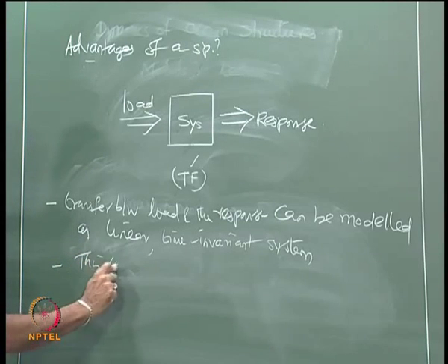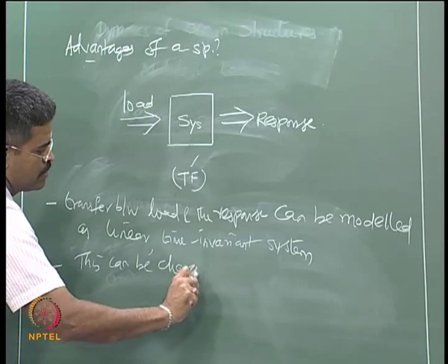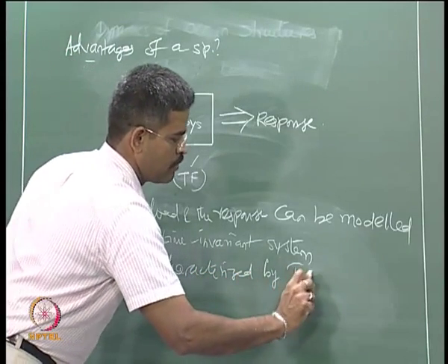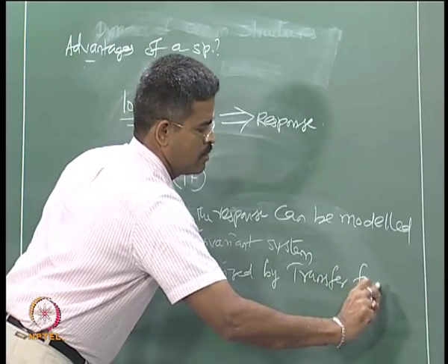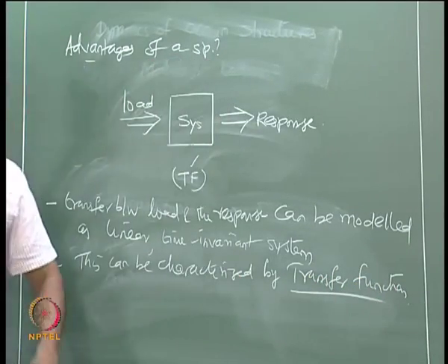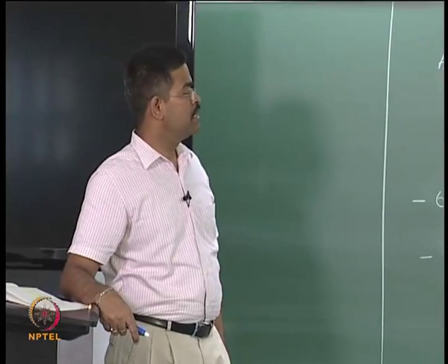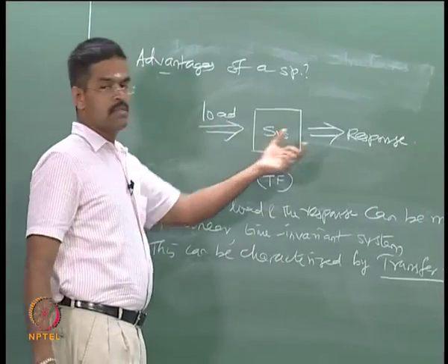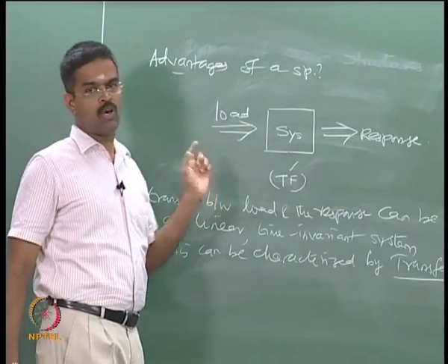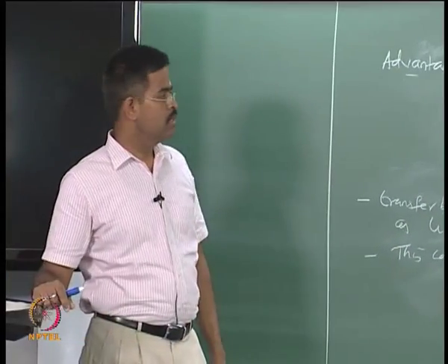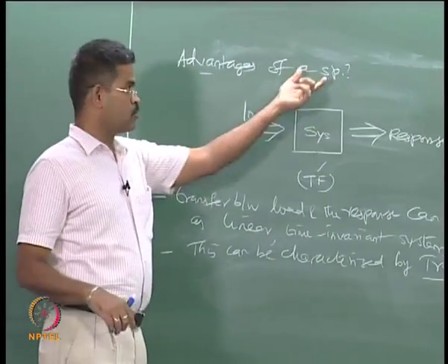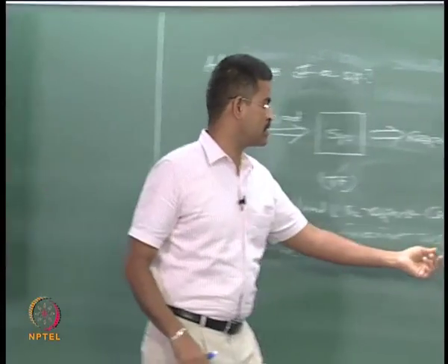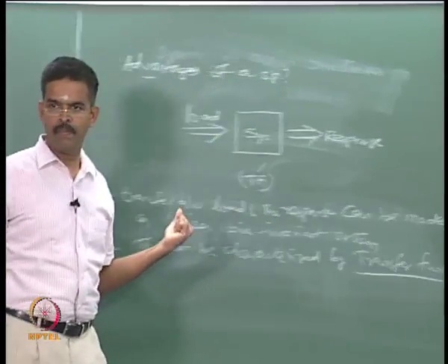This can be characterized by a transfer function. So our objective is to derive a transfer function which gives me the connectivity between the load acting on the system and the response received by the system because of the load acting on it. Fortunately, if the system qualifies to be called a stationary process, then I can characterize this transfer function as a time invariant problem.